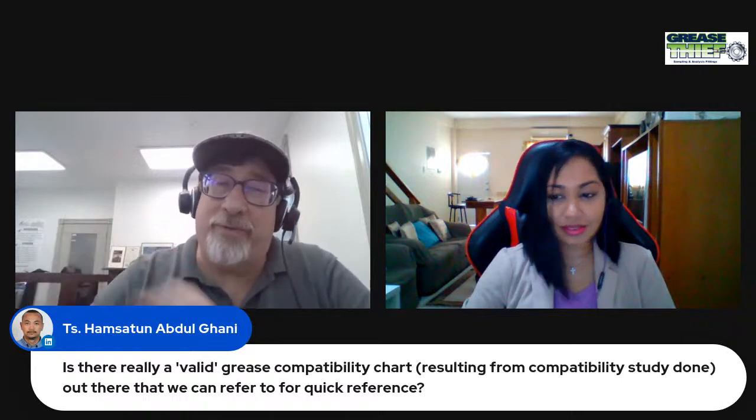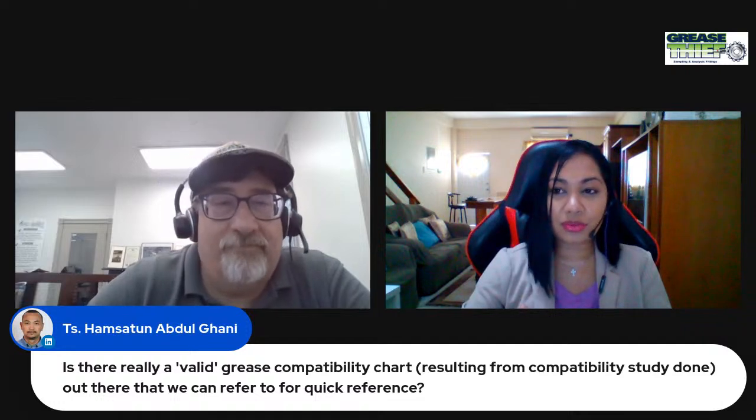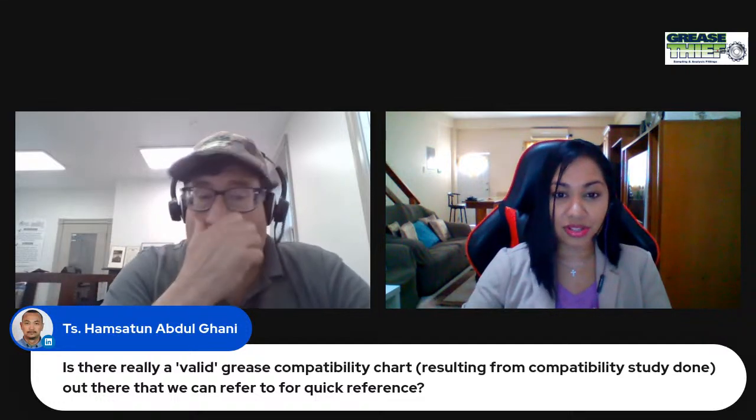Yeah. And again, otherwise, we need to test it. Yeah, testing, I always agree with the testing method because that's what you see exactly what's going on. It uncovers every single thing. So even though you may go to your manufacturer, your OEM, and ask, what is the grease chart? Because I know some OEMs also do grease charts with their compatibility stuff. Yeah, and sometimes that may be more accurate to their greases. But if you're using different OEMs, they will not be the same. So that's a good thing to think about as well.